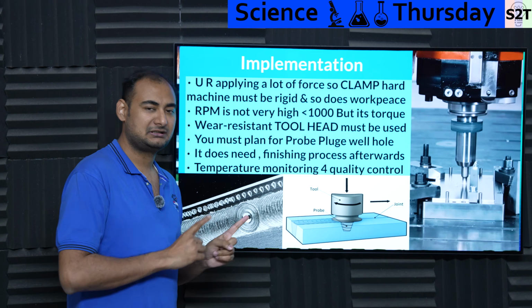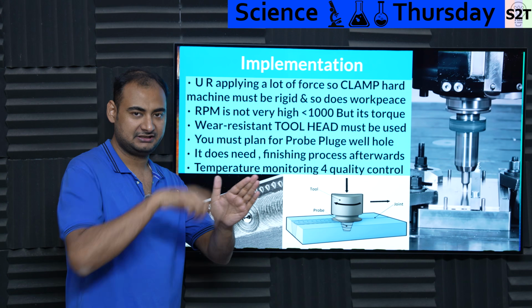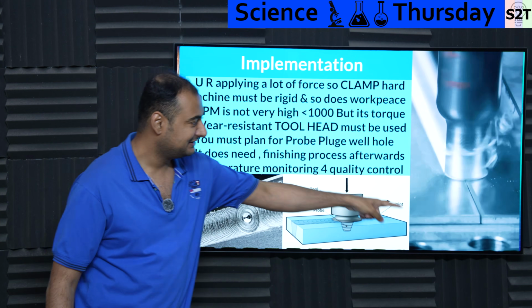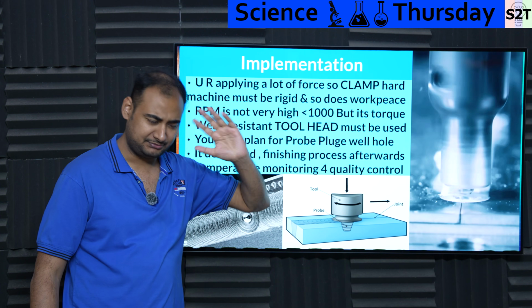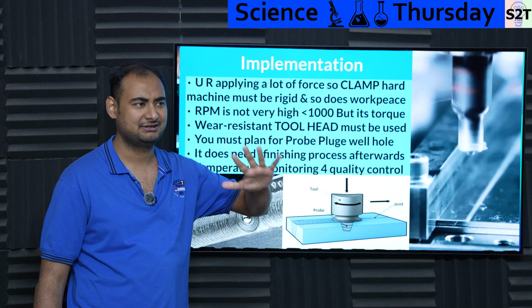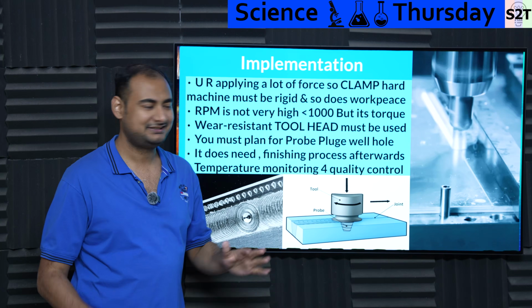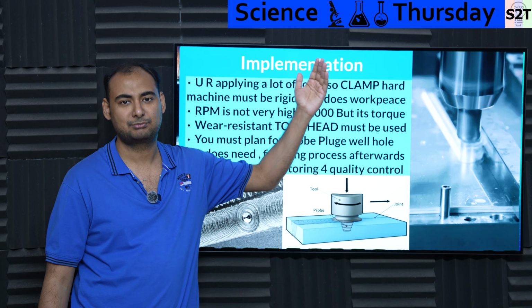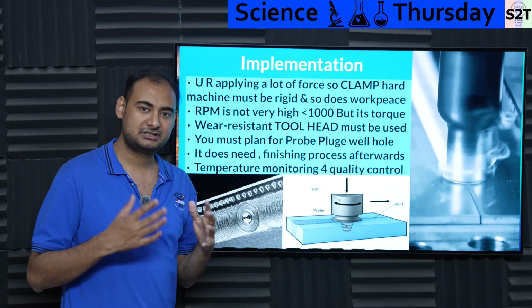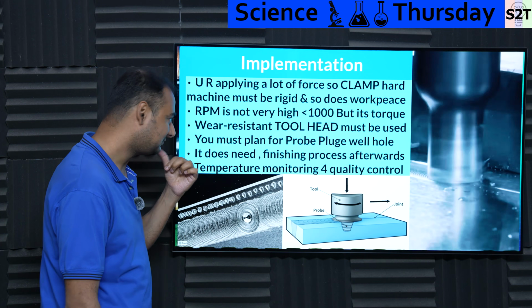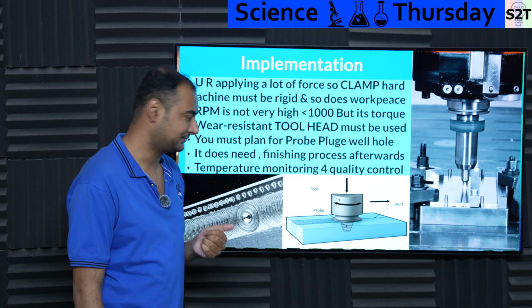But it's not a complete process. Laser welding is like, you have the material, laser weld, throw it away, the end, process done. This is not like that. Generally, you're going to leave a burr. A lot of people are trying to make burr production almost negligible. But as a cautionary tale, you have to run a deburring process on it. Again, not a serious load or something heavy, but you do need to have it. So a finishing process is a requirement.